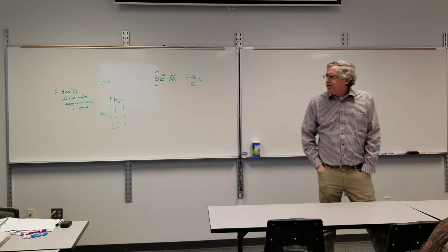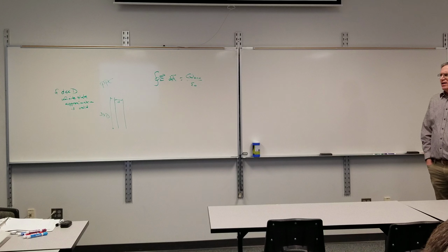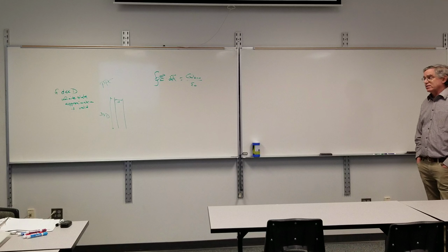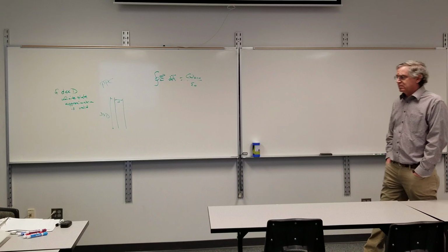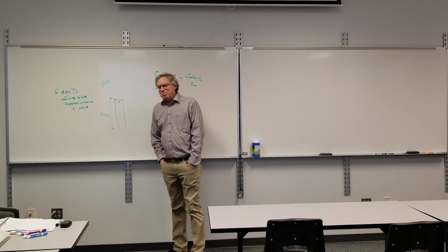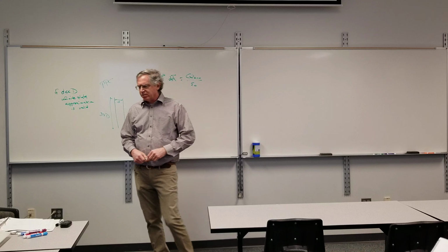Typically, if you need a number, if little d is less than 10% of big D, the approximation holds. If you exceed it, it's still not a bad approximation, but you're getting more and more off, as the plates get farther apart.